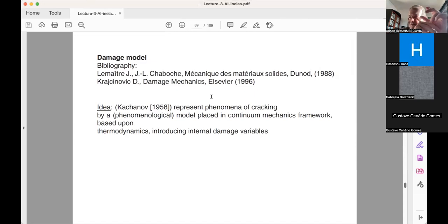In reality, in linear fracture mechanics, you have to have a crack, and then you study whether this crack is stable or unstable. So nowadays, there's something called the phase field approach, because they took this approach of linear fracture mechanics and extended it. But again, they had to know where the crack is. So I would say this type of theory might apply credibly in the case where the cracks are easily recognized and identified, and then you want to study the stability of a structure which already has cracks.